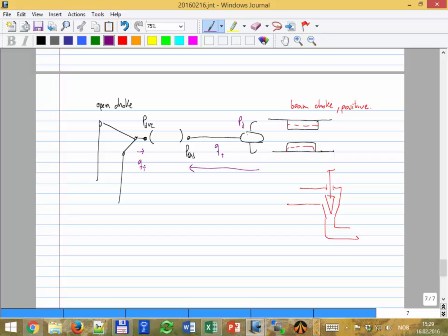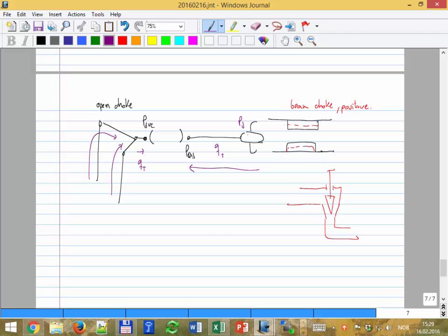I have two ways. I can calculate it from here, or I can calculate it from here. So which one should I use? Are there two pressures at the suction of the compressor? No, there are two, do you think? No, one junction. There should be only one. So really what's happening here? What if I tell you, I know how much is coming out of here, but I don't know how much is coming from well 1 and well 2. That comes from flow equilibrium.